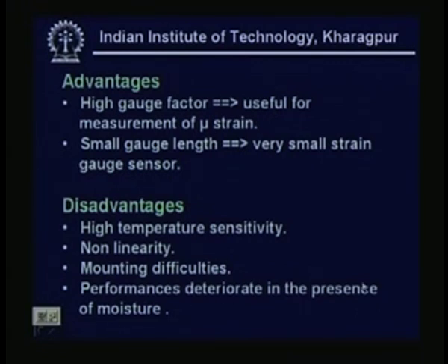In instrumentation, you will not necessarily measure without moisture. Sometimes you will have to measure where superheated steam is there. Sometimes you have to use corrosive liquids, sometimes a gas which is very hostile in nature. In that type of situation, a semiconductor strain gauge is not very suitable.